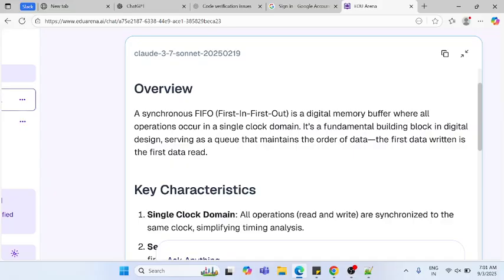But now what is the difference between static RAM and FIFO? FIFO does not have any address, but it will have a fixed entry or fixed depth, right? It is called first in, first out. It's a kind of queue, so the queue depth can be specified. So what happens when we start writing the data, at a particular clock frequency, the data will be written there.